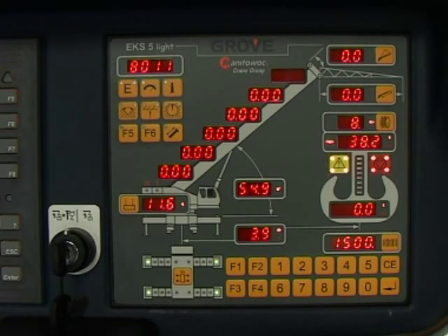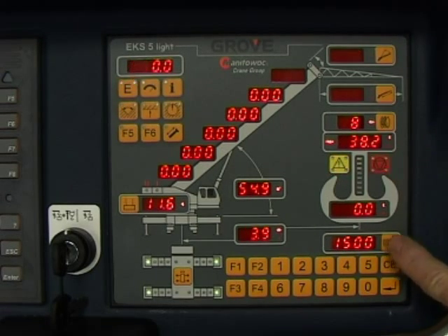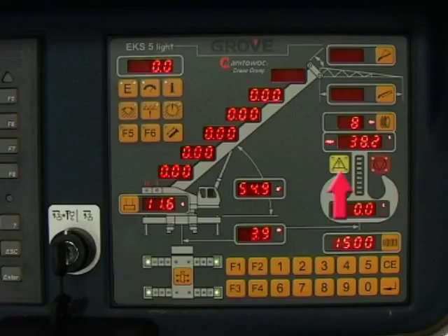If less than 48 hours, the last entered reeving and RCI operating codes are loaded as shown. If these still correspond to the crane's current operating configuration, you can press the enter buttons for reeving and RCI operating codes. This will remove the signal points after the entries to accept the reeving and RCI operating codes. The pre-warning lamp, shutdown warning lamp, and error button LEDs will then go out to make the RCI ready for